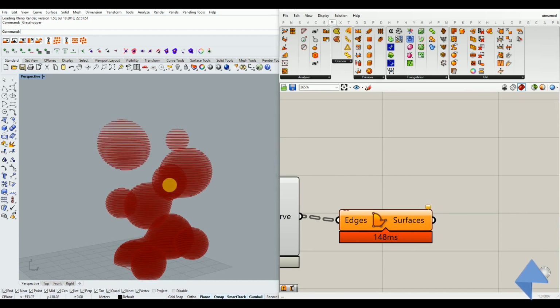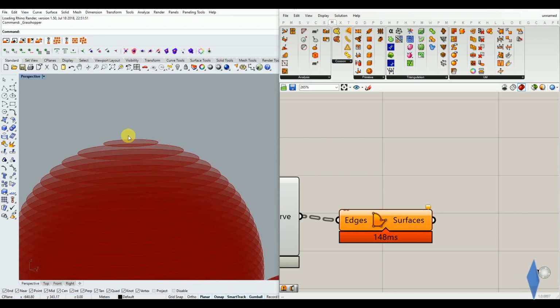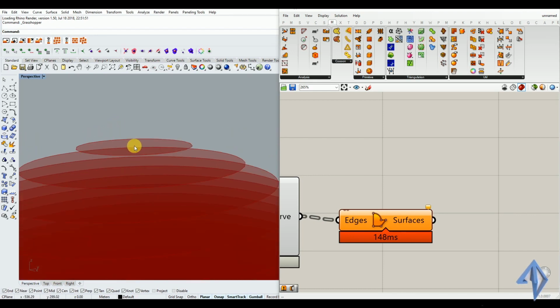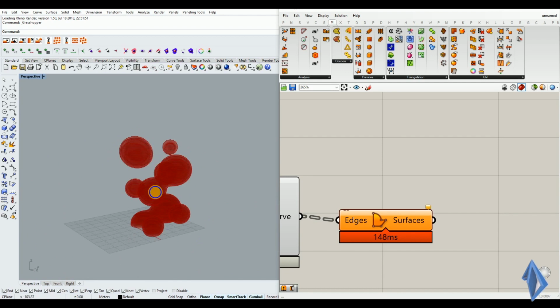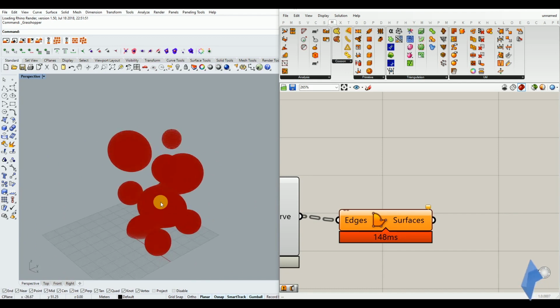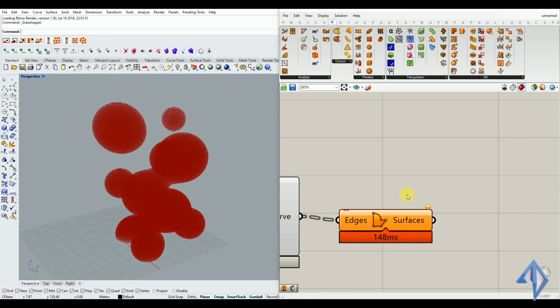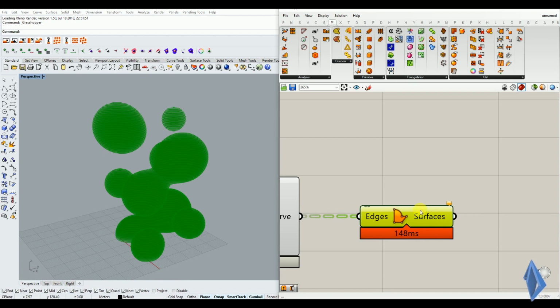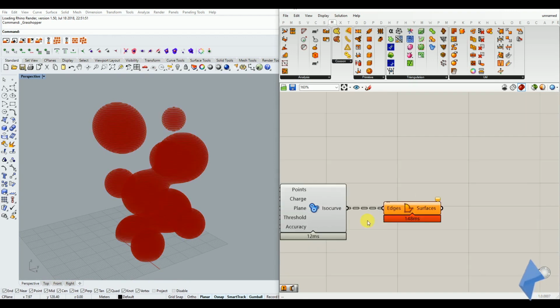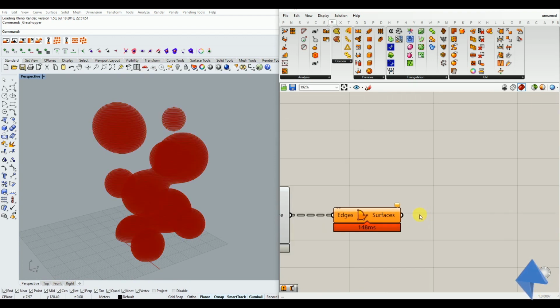This is just in case, because after this is completed, there are very minute other curves that are not visible to us right now on this viewport, which might not have been converted into some of these surfaces. There might be 1 or 2 curves, so that's why it's returning this kind of a result, and your component is yellow instead of white. So we don't need to worry about that. We can just go ahead and extrude now all of these into some 3D solids.